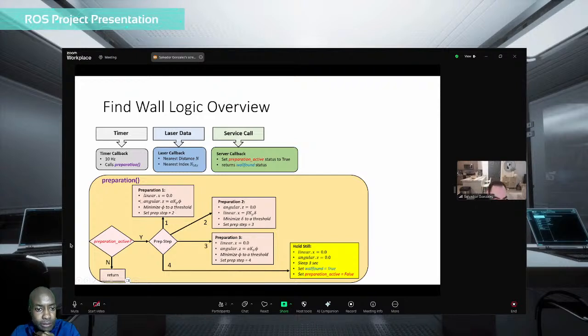And what it does is it has a specific error calculation, and I minimize that particular error to some threshold. So, for example, the angle error I have set to like 5 degrees or 5 units, which I think is maybe like 2.5 degrees. So if we're within 2.5 degrees of where I want to be, then okay, good enough. Otherwise, the robot, because of noise, because of real world complications, it might never settle.